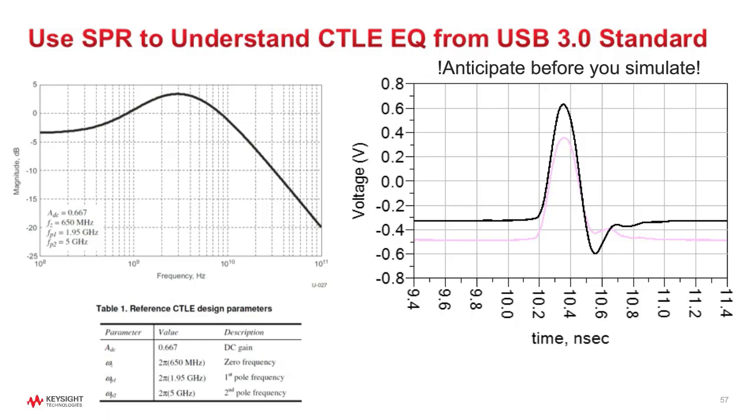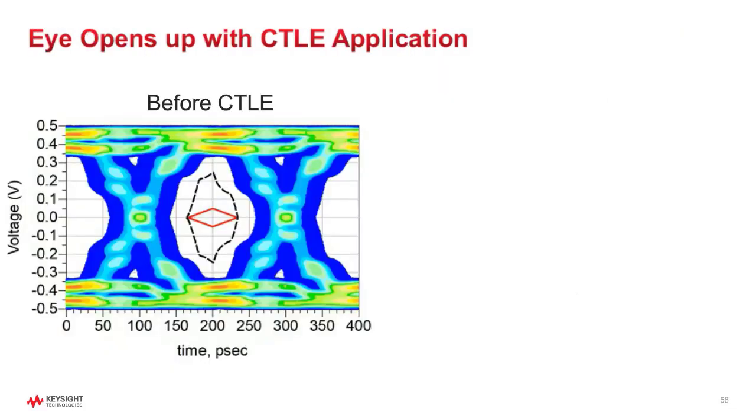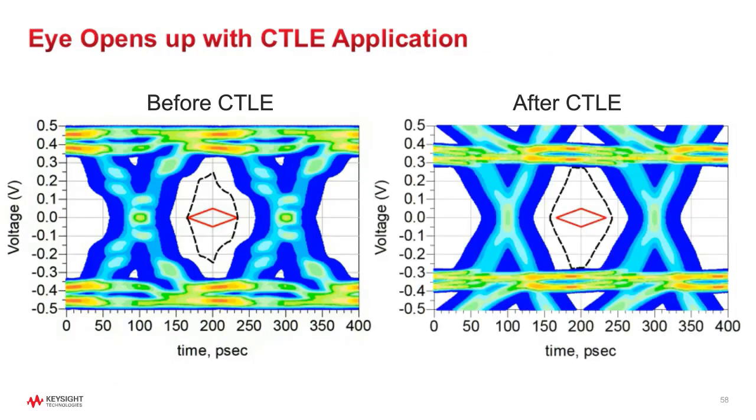So there's a decrease due to a low frequency CTLE around minus 3 dB. That means it's going to decrease the overall eye. But if you look at the gain here at close to 3 dB, it actually increased the peak. That's why also in the eye diagram, we see that there's a little overshoot because we have a gain.